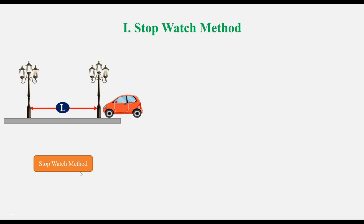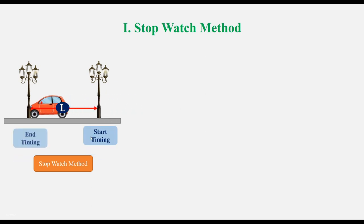Stopwatch method. Here you can mark a small section of length L on the road and find out how much time a vehicle will take to traverse this length. So you can note down the start time and the end time. That is from front to front.